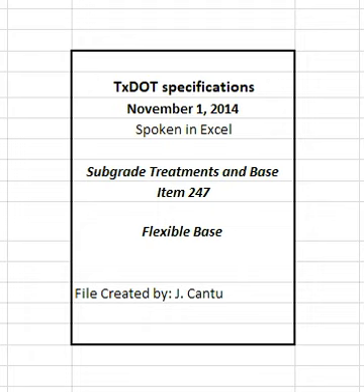Begin rolling longitudinally at the sides and proceed towards the center, overlapping on successive trips by at least 1/2 the width of the roller unit. Begin rolling at the low side and progress toward the high side on super elevated curves. Offset alternate trips of the roller. Operate rollers at a speed between 2 and 6 miles per hour as directed.